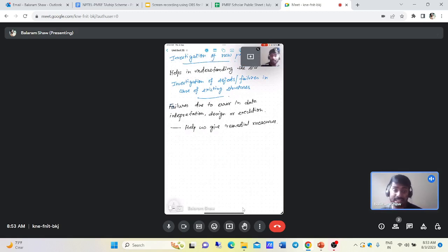Also, let us say in design, as I said, we have some assumptions, right? We are simply doing the interpolation of 2 points. Let us say we have 2 locations, and we know the soil characteristics for these 2 points, and we want to know somewhere between them. So we assume that it will go like that, and we do simple interpolation for the soil characteristic profile, and that can also lead to some design problem, right? So that kind of assumptions or the material characterizations, the deformation forecasting, those things also can lead to failure.